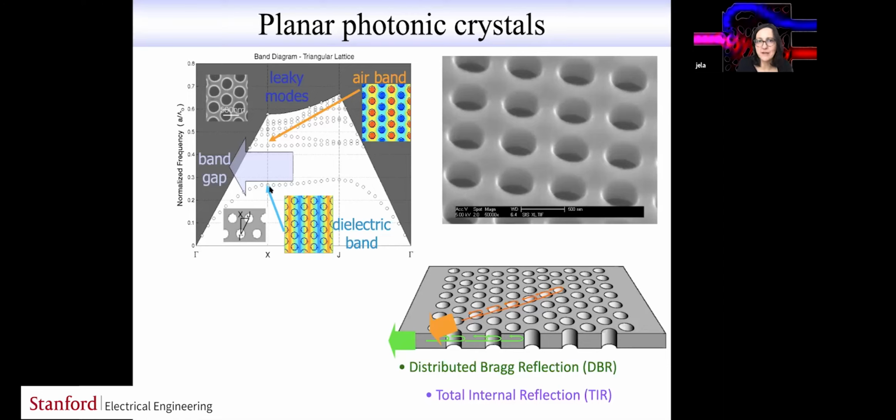So you expect, if you look at a particular K point of the band diagram, like this X point here, which we'll see what that means, but let's say look at that X point, you're expecting your electric field here and here to be represented by Bloch states that have the same symmetry and the same periodicity, but the one with lower frequency would tend to concentrate electric field in silicon, while the one above would tend to concentrate the electric field in air.